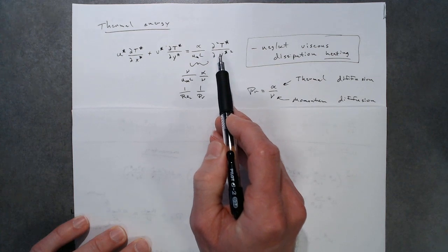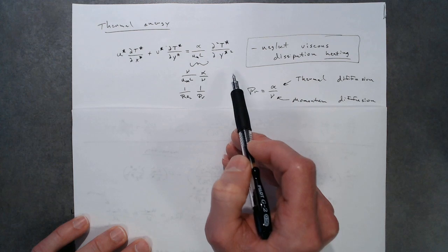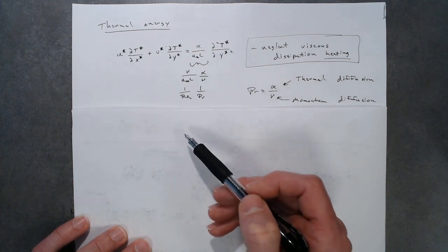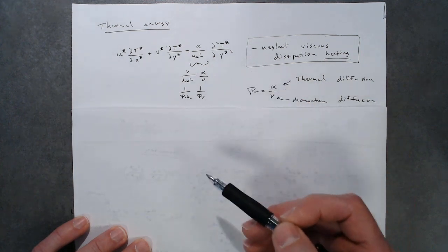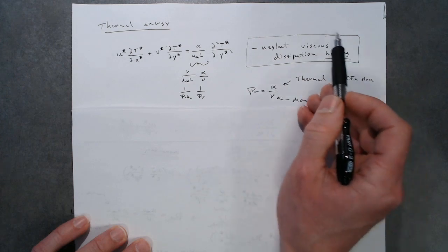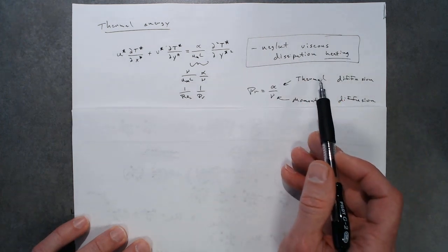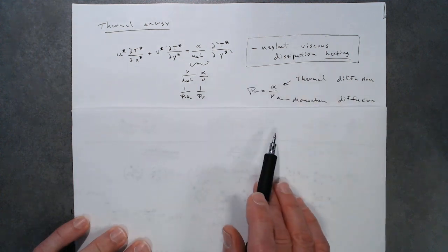We remember in the full thermal energy equation, there was another term that depended on viscosity and the square of the gradient of velocity. Well, we said that term corresponded to the conversion of mechanical energy into thermal energy via viscous heating. But that is usually negligible in most of the cases that we consider, in this class at least. And so we're going to drop it.